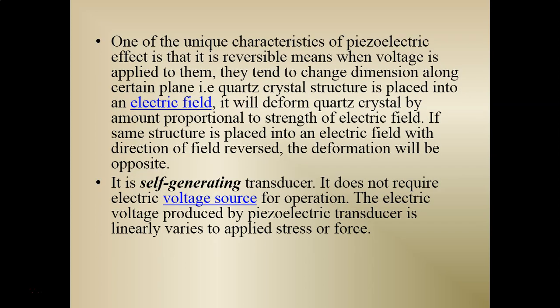So another unique characteristic of piezoelectric effect is it is reversible. That is, when voltage is applied to them, they tend to change dimensions along certain planes. So already we are seeing here under electric transducer that if you are giving any force, stress, it is converted to electrical form. So reversible means what? Again, from the electrical form, it can be converted to the physical quantity like stress or force. That is, the crystal dimension will get changed when we are applying electrical field.